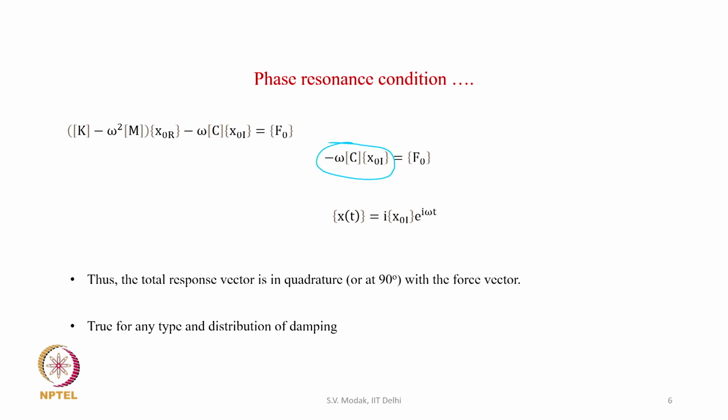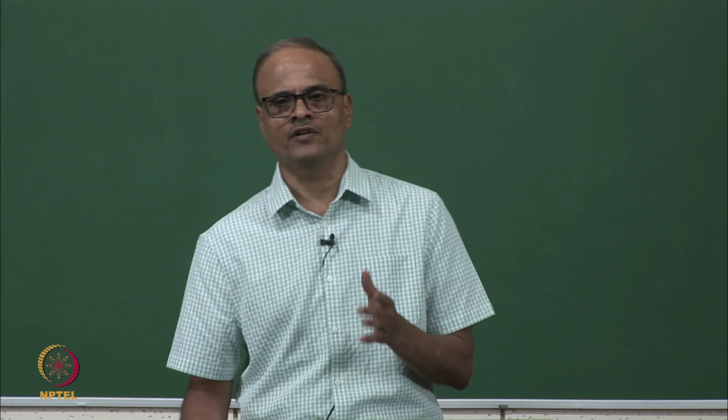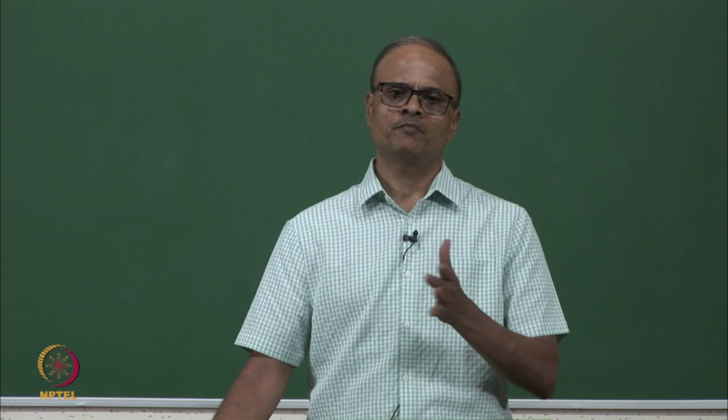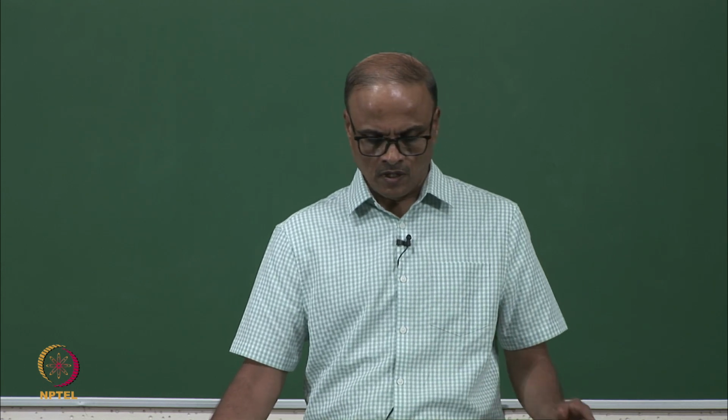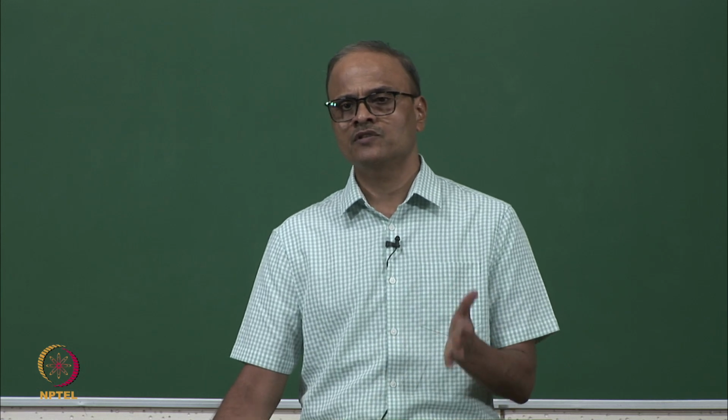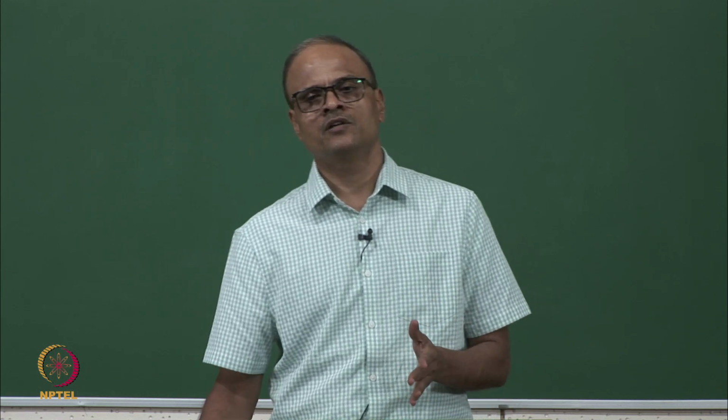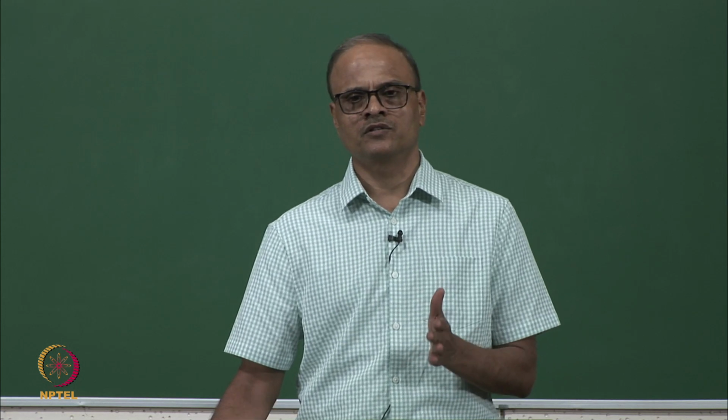So, this phase resonance condition will have to be satisfied for excitation of a normal mode, irrespective of whether the damping is proportional or non-proportional. We analyzed this for the case of viscous damping, but this condition can also be proved for the case of a system with structural damping.